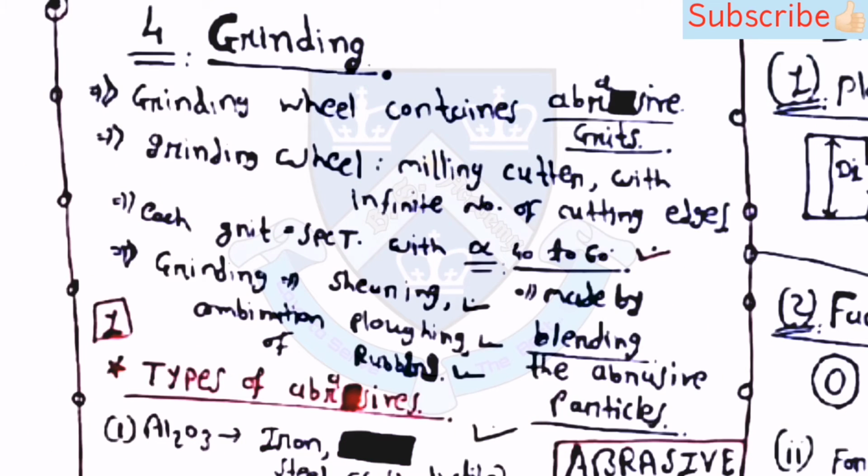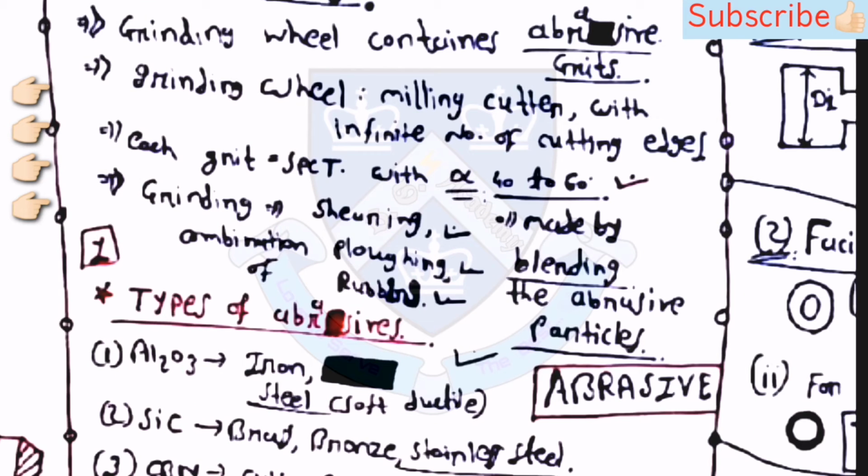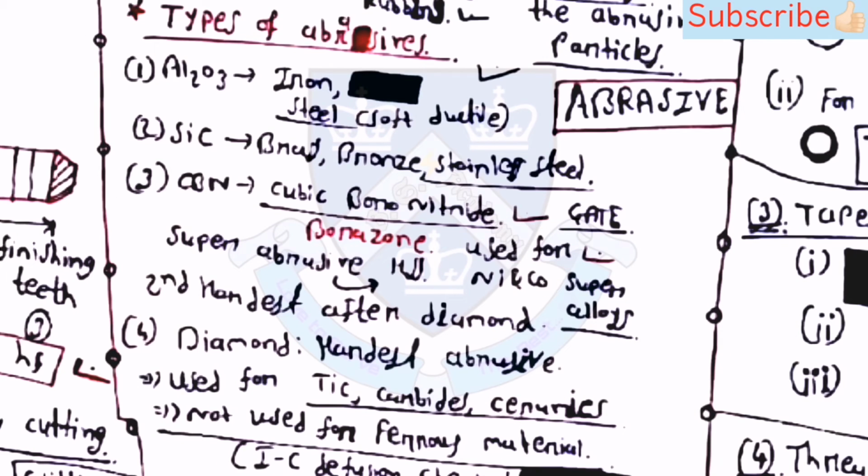Grinding process. A grinding wheel contains abrasive grains, and a grinding wheel is like a milling cutter with an infinite number of cutting edges. Each grain is like an SPCT with a rake angle alpha between 40 to 60, where SPCT means single point cutting tool. In grinding, it is the combination of shearing, plowing and rubbing. Then there are types of abrasives.